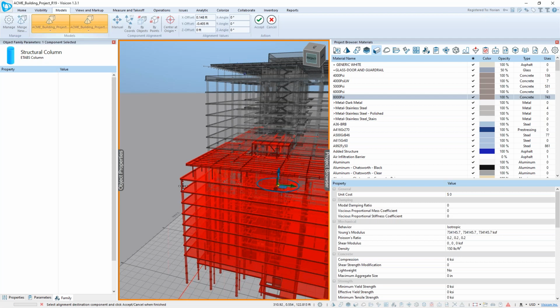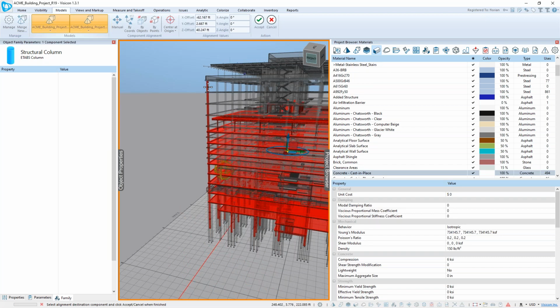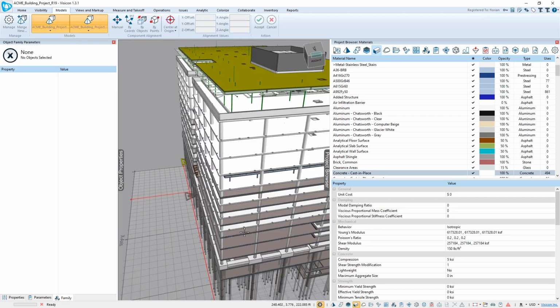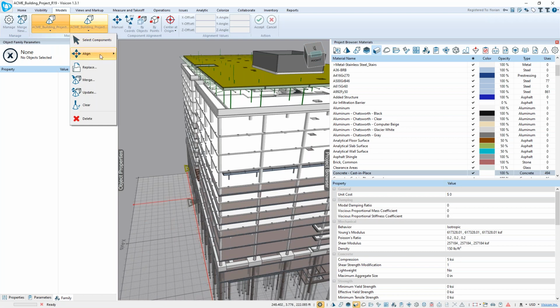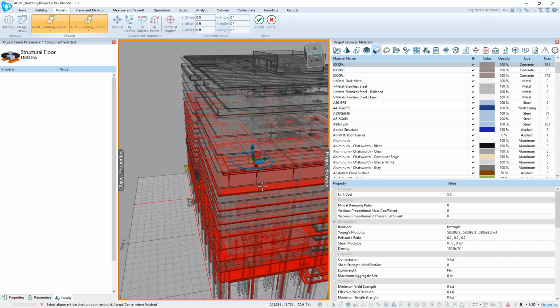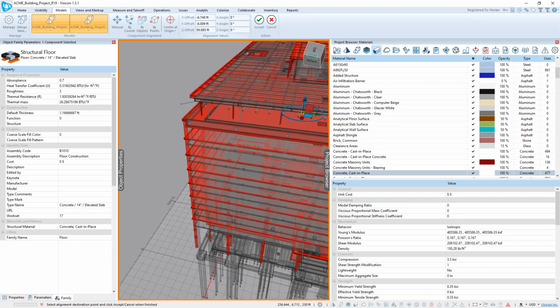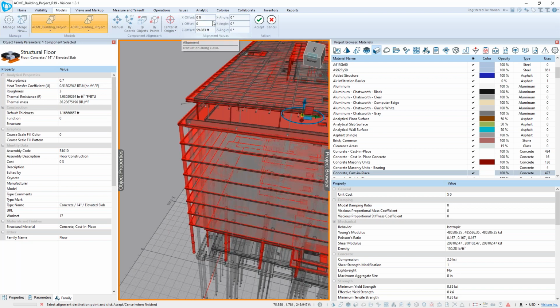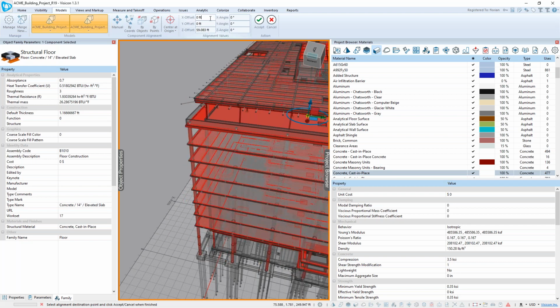So we've now done a proper XY alignment. We see we're still off in the vertical, Z, no problem. We come in, we're going to do align by points. And what I'm going to simply do is take the top, I'm going to click the top of the uppermost ETABS model and click the top of the uppermost REVIT model. I'm going to zero out the X and the Y adjustment and accept it. It is that simple now for us to have aligned both of those models.